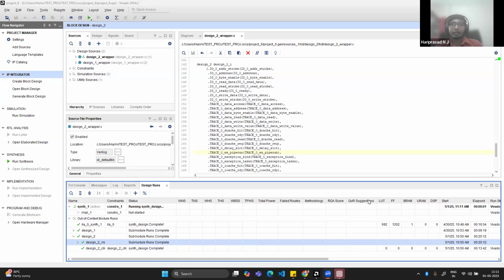But in case of partial reconfiguration, we usually use some Pblock-based approach and say this is the partition we have to configure, this part of the design. Then without powering down other logic, only that part will be configured. That is why we generate partial reconfiguration bit files. So each bit that is required for a particular switch may have some address.